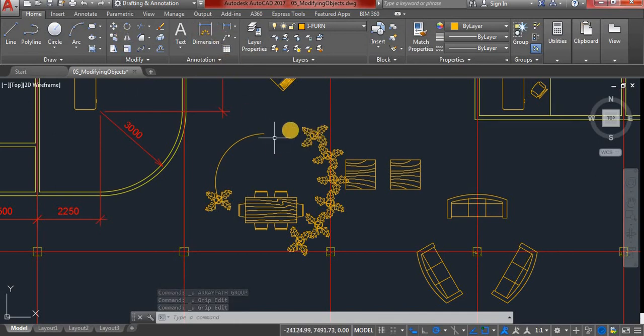Now there is a question in my head. When I put the plant in here, why didn't it follow the path that I made? The thing with AutoCAD is that it goes with the positive polar tracking, which is counterclockwise. It goes in that direction. In order to fix that, I will change its location so it follows that path.